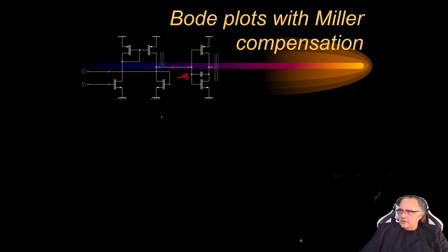So if I quickly redraw the equivalent circuit of the output stage of the second stage, of this internal node, I have these transistors, and then I can represent these capacitors, say the Miller capacitance, with a certain equivalent capacitance. And this capacitor will be very big. Why? Because there is the Miller effect acting on top of CM here.